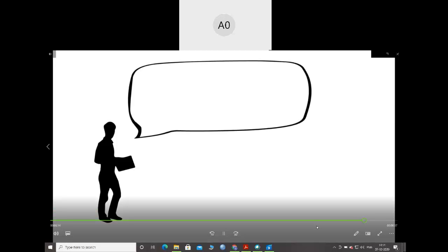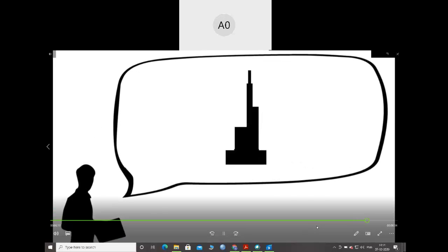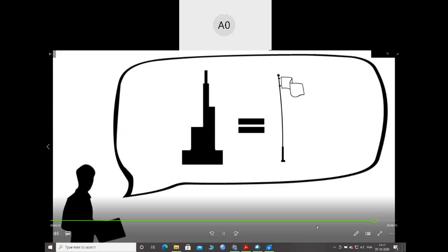Now, I just gave an in-person seminar at AIA New York, and one of the participants in that seminar asked, what about a really tall, slender building? Would that kind of behave that way at the scale of the building? If you were worried about buckling for the building, would it behave like a flagpole? And the answer is kind of yes, but in practice, buckling would not be the biggest issue. In other words, you'd be much more concerned about other things. First of all, buildings aren't quite that tall and slender like a flagpole. And secondly, there would be other factors for the building that would require beefier structure, and it would be unlikely that buckling would control. But yes, same principle.